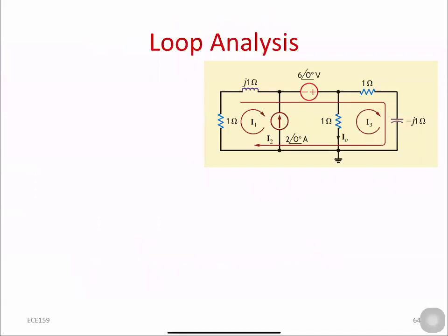All right, so this is another circuit, and the loops are already given to you. So you have to use loop analysis, and you need to find out I naught in the circuit. So find out I naught, and already loop current directions are given to you, right? So you can either choose these directions. So it's already given to you. So I will just use the same directions. So the first thing I know is the I1 is nothing but, so the direction for I1 is in opposite direction to this already current source which is given to me.